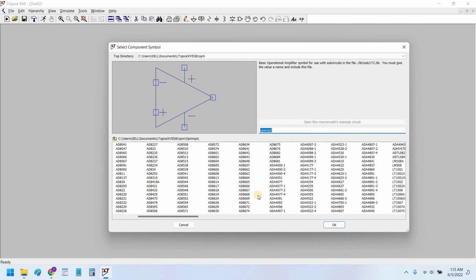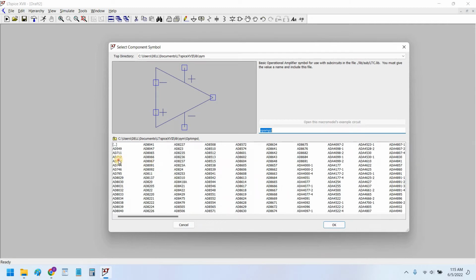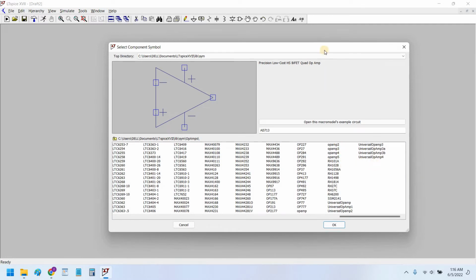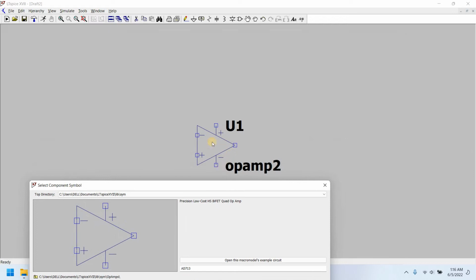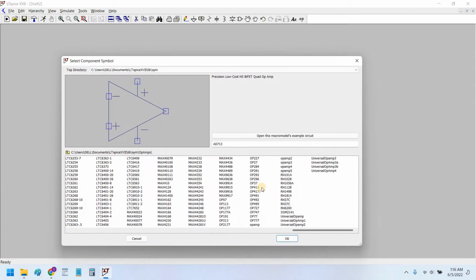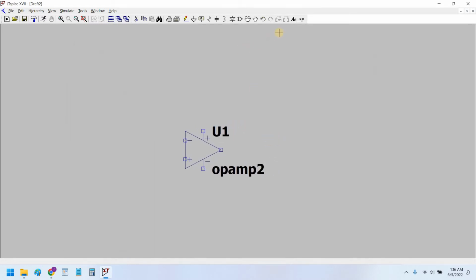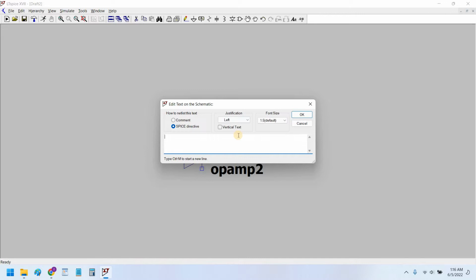So we can randomly choose these already available Spice models in LT Spice, or we can use a generic OPAMP, as I have put this OPAMP symbol here, and upload its Spice model from a third party vendor like Texas Instruments or Analog Devices website. Just like in my previous video, I would upload the Spice model into our schematic, and I would write a Spice directive again,